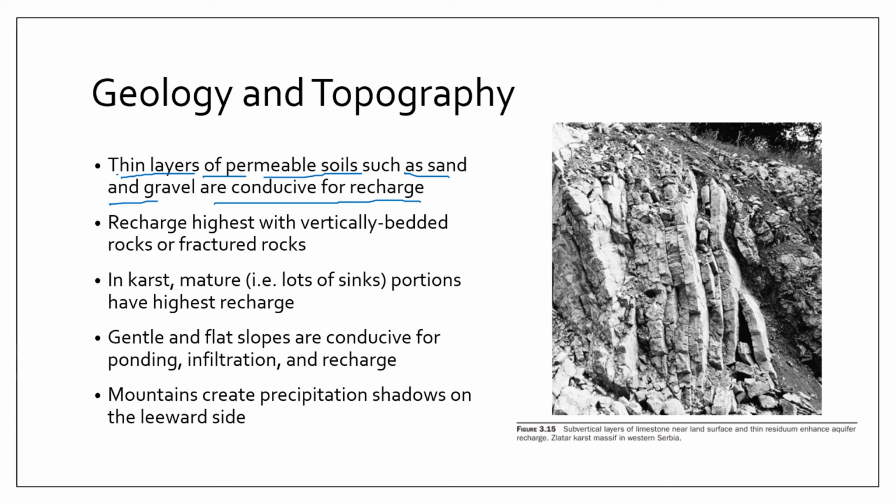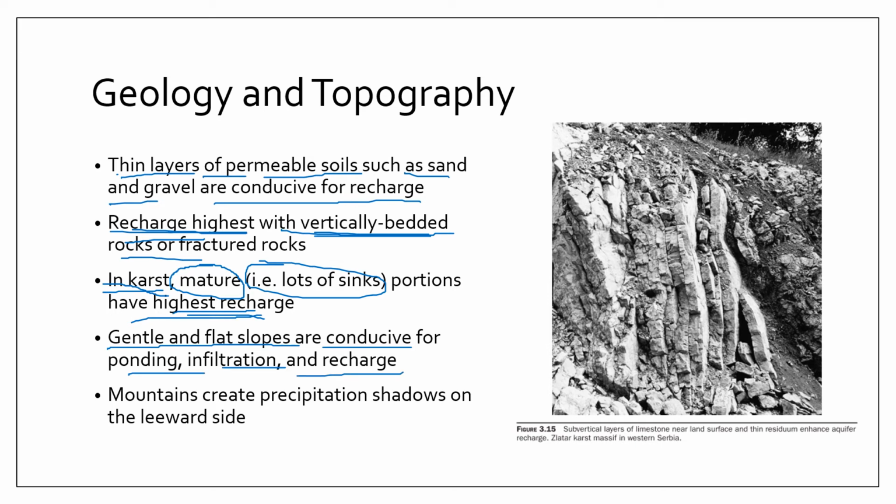And then if you're talking about rocks, vertical beddings, vertical fractures, and vertical faults have the highest recharge rates. And then if you're talking about your karst or your limestone areas, the mature karst, or the areas with lots of sinks and sinkholes, have the highest recharge. And for topography, typically the gentle and flat-lying slopes are the most conducive for ponding, infiltration, and therefore also recharge.